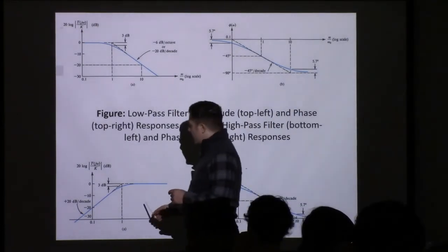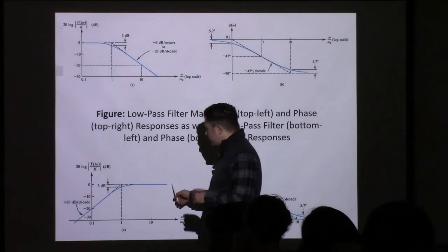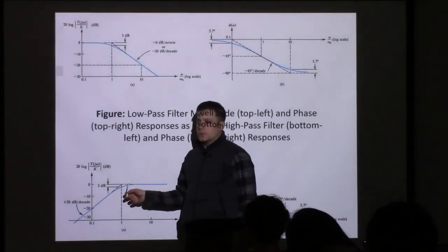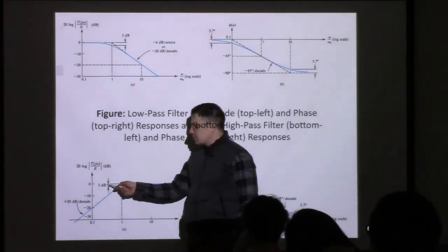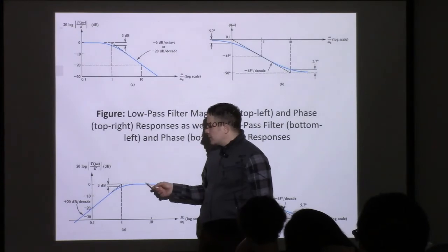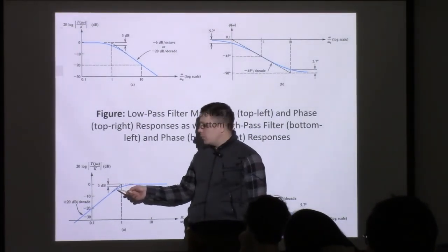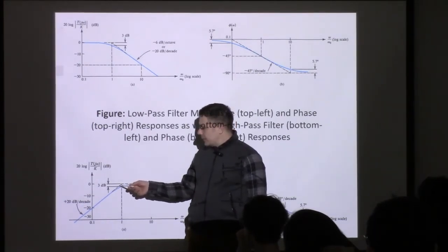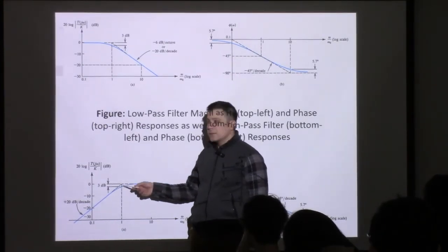This is the high pass, and the gain right here is K, which for the high-pass filter is actually equal to 1, or 0 decibels. You'll note here that it says 3 dB. There are two ways of drawing this figure. There's the ideal way, which has this sharp inflection point, but it actually curves a little bit more. Honestly, for the purposes of this, I'll accept either 0 dB or negative 3 dB.